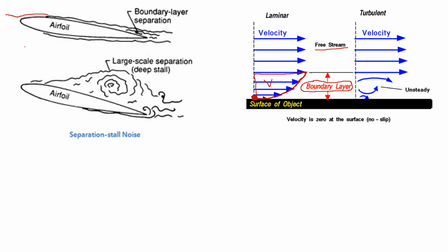This boundary layer separation is very important when we study aerofoils or bluff bodies, so that we can see where the drag forces will occur and how we can reduce the drag force. In the case of an aerofoil, we want this boundary layer separation to occur further down the tail of the aerofoil, because then it will result in an increased lift.